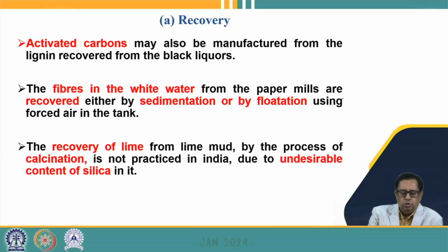Similarly, we can also go for the fibers which are there in the white water, so they can be recovered by the sedimentation process or by the flotation process. So we can use air flotation here, so that the fibers which are lighter in nature can come to the surface by the air flotation process, and then these fibers can be separated out from the white water and then reused, and this will also decrease the load on the wastewater treatment.